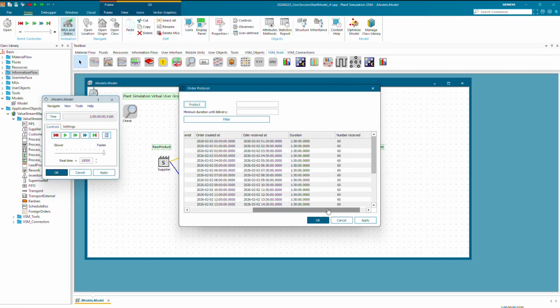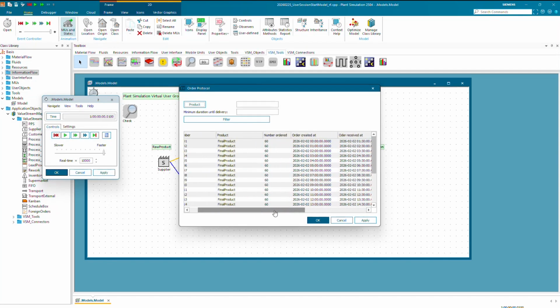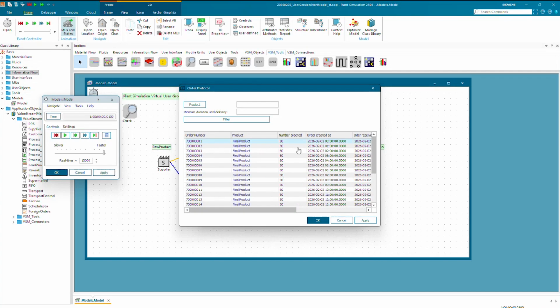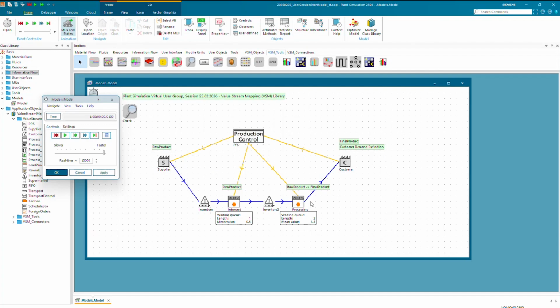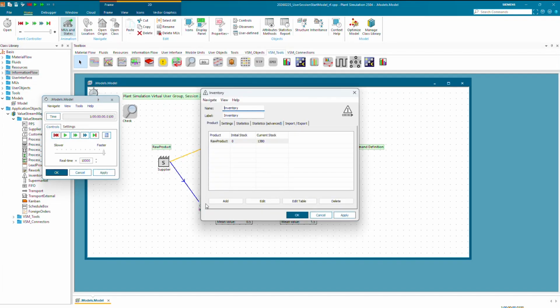It should be quite simple with the time or with the static calculation. Each order has a certain number ordered at. So every hour, this basically is an entry. Customer is ordering 60 parts. The 60 parts are distributed to this station, and to this station you have a local order which is then activated once this inventory holds enough parts for the whole order, and then the order is activated and then basically pushed forward to the successor. So with additional statistics, this behavior can exactly also be looked at.